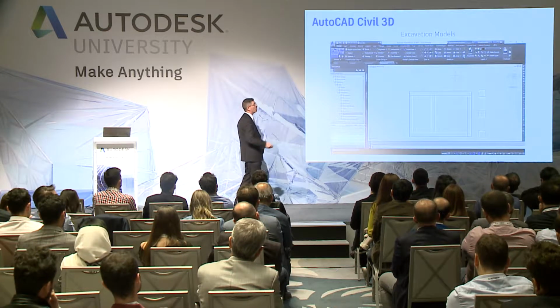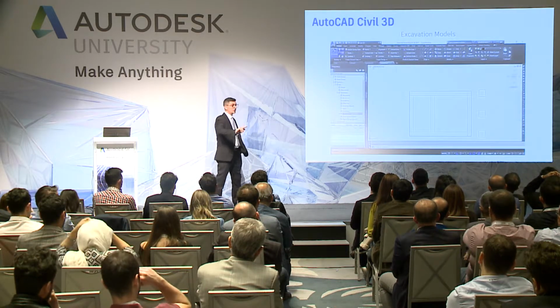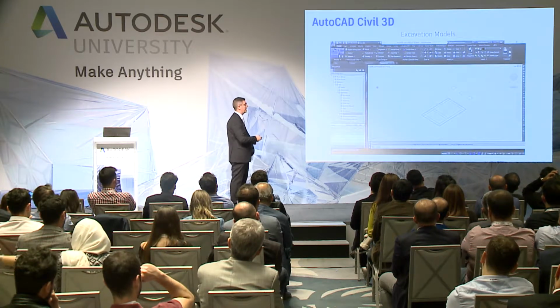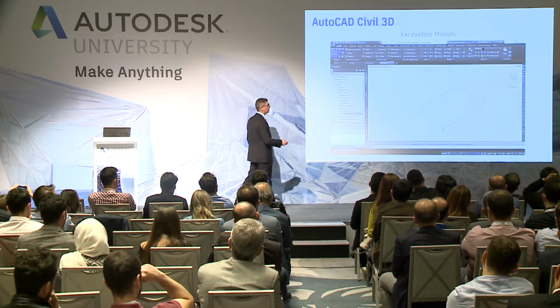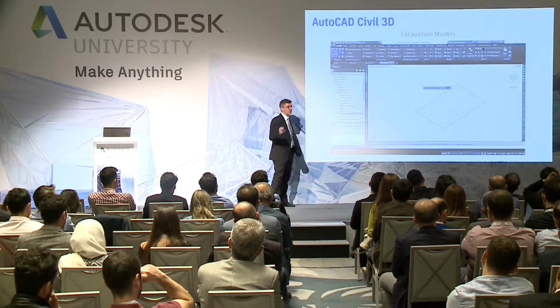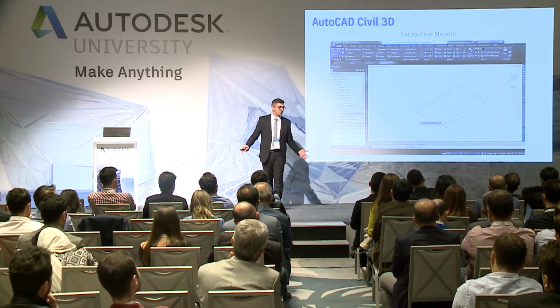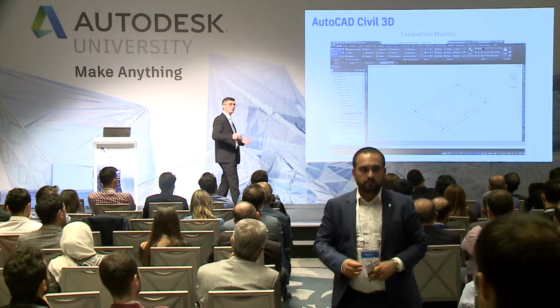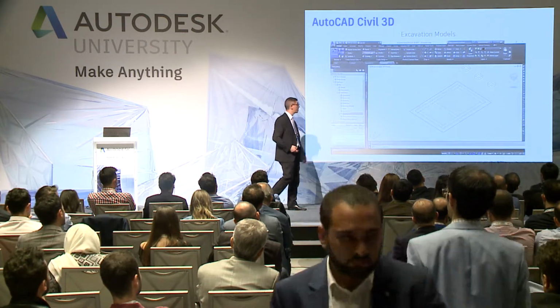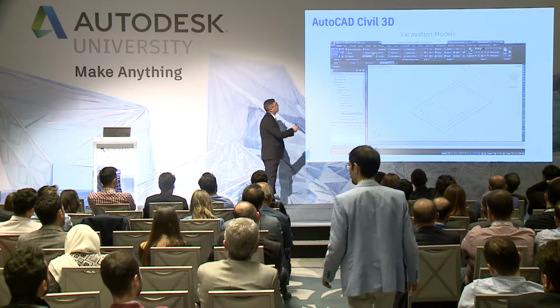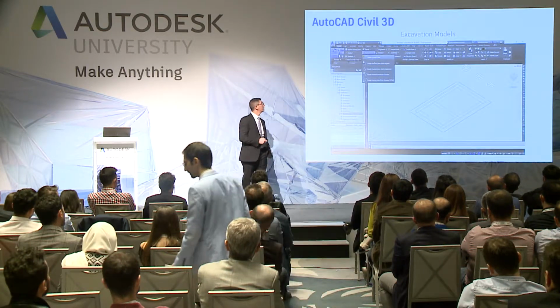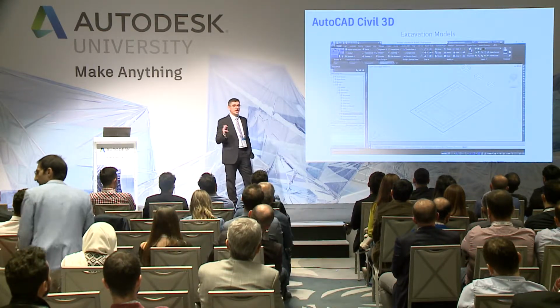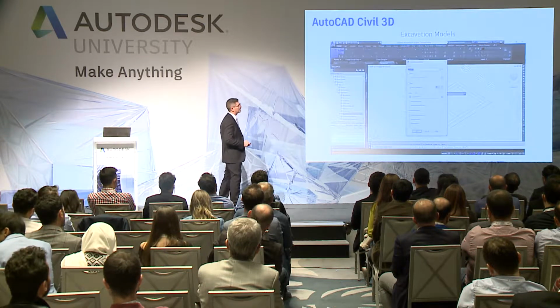I can start drawing a polyline, and then I switch to convert this element. Before doing this, I do a sort of offset, because I want to have a safety space to work with the workers, or because I need to move the machine in my excavation. Then here, I can start with the feature line. I'm starting from converting a 3D polyline. Then I can select OK.